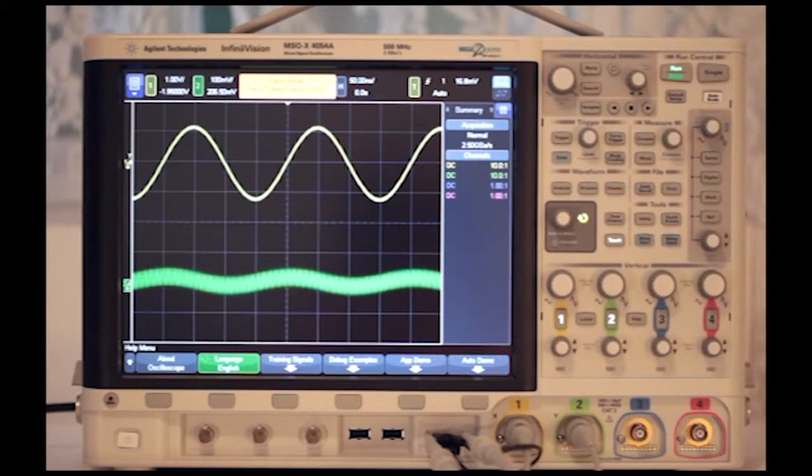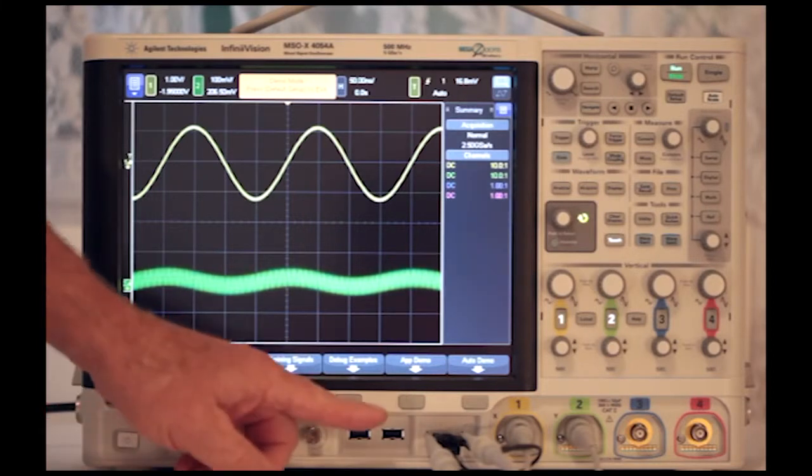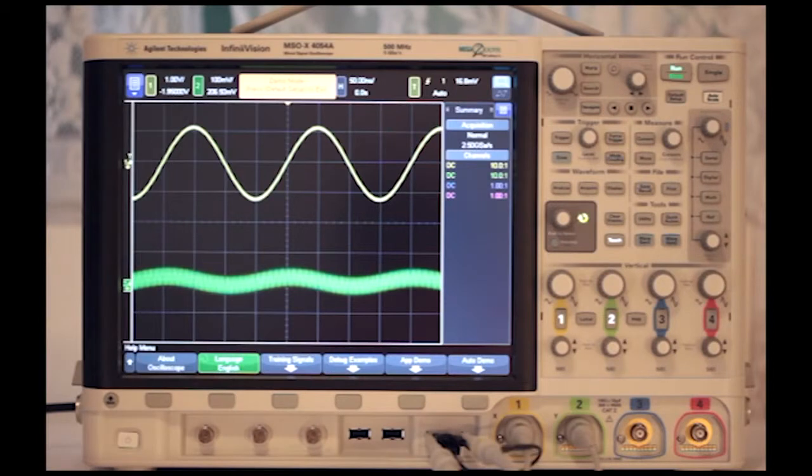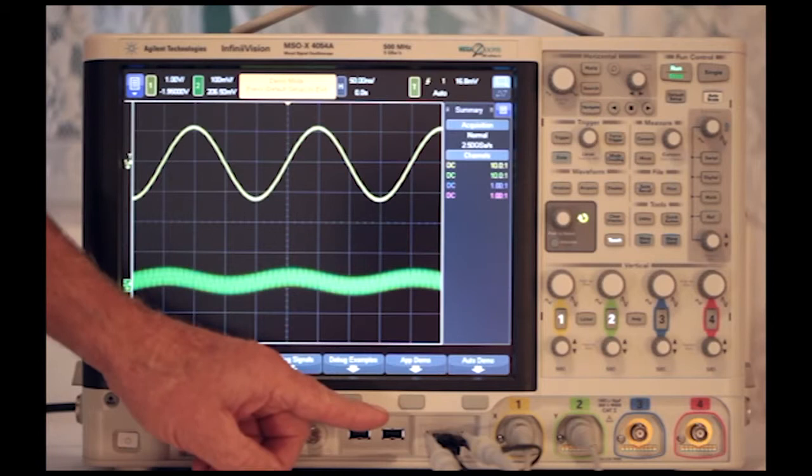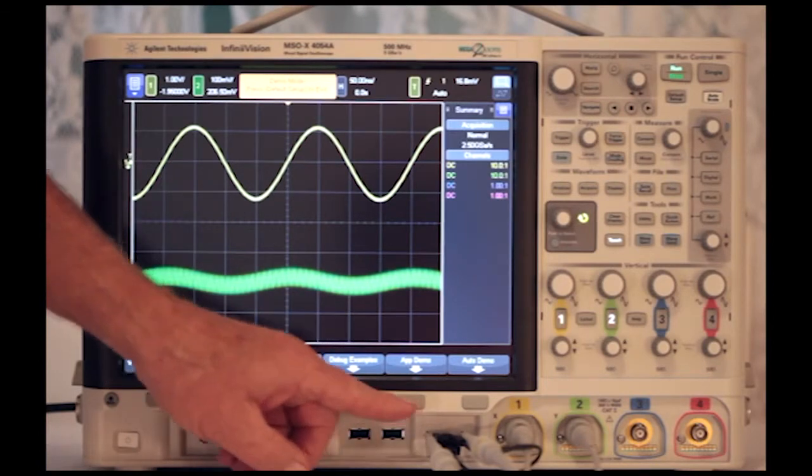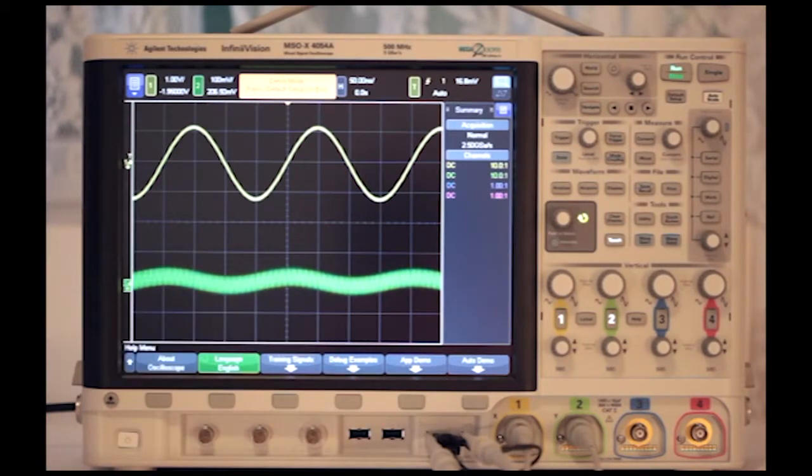To get started, perhaps before powering up the oscilloscope, you'll need to hook up two standard 10-to-1 passive probes equipped with hook tips. Previously, the probe should have been compensated and color-coded to indicate the proper channel. If you look closely at the output connections of the oscilloscope's front panel, you'll see that there are two terminals labeled Demo 1 and Demo 2 with a common ground.